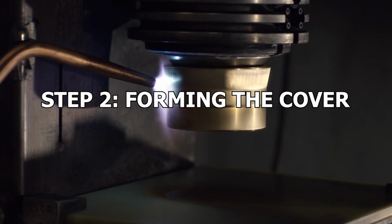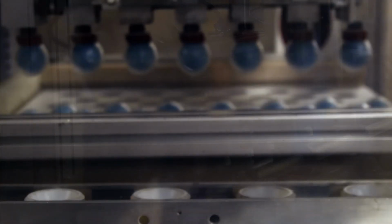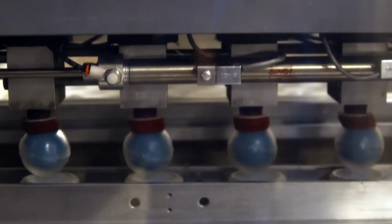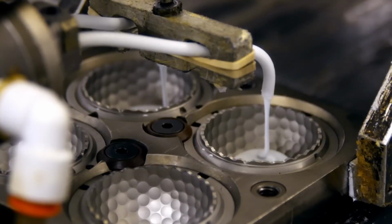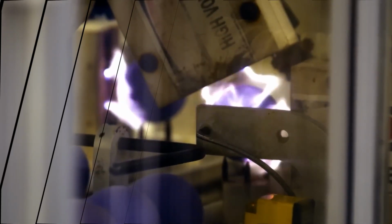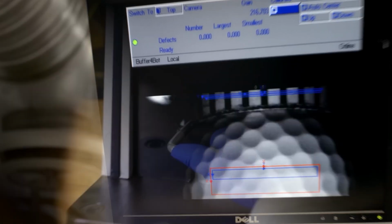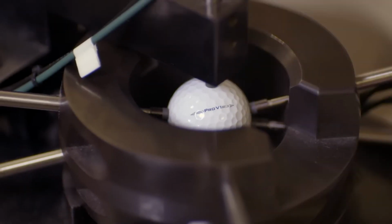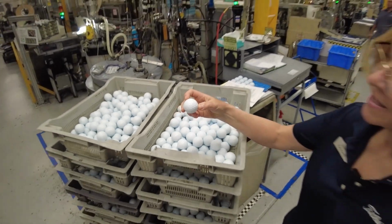Step 2. Forming the cover and dimples. In the injection molding process, the core is centered within a mold cavity using pins. Molten thermoplastic is then injected into the cavity surrounding the core. The combined effect of heat and pressure causes the cover material to flow and bond with the core, creating the dimpled pattern and final shape of the ball. Once the plastic cools and hardens, the pins are retracted and the finished balls are extracted.